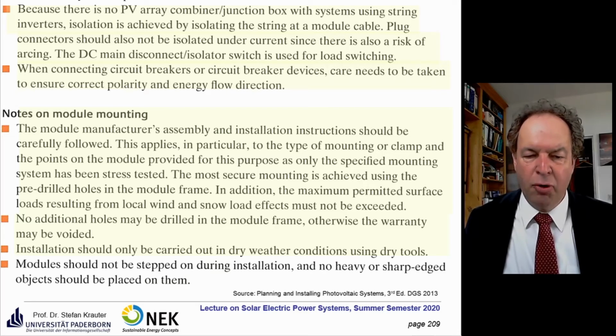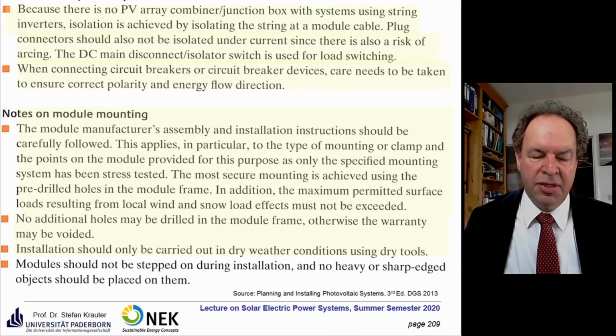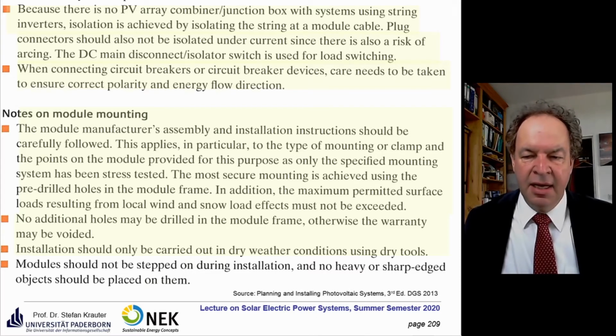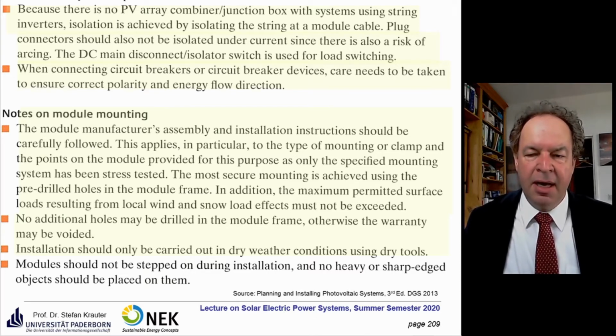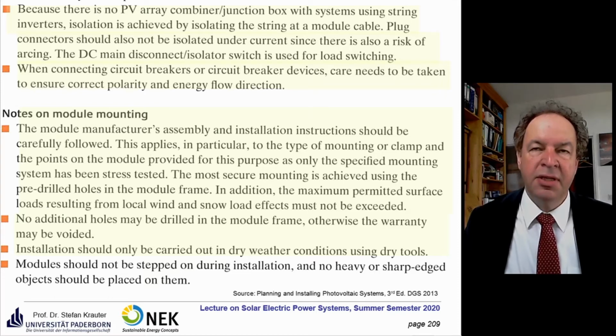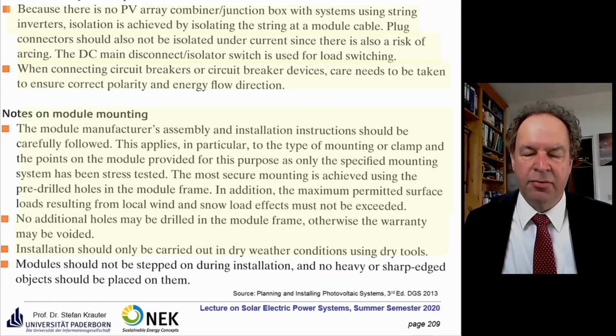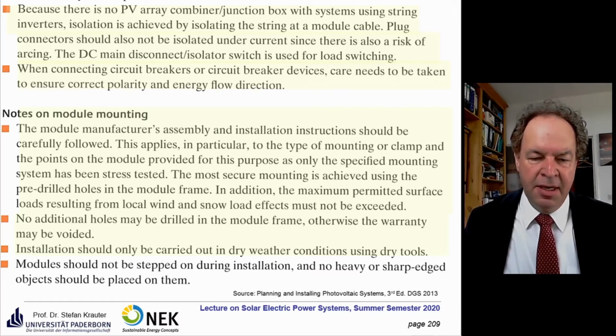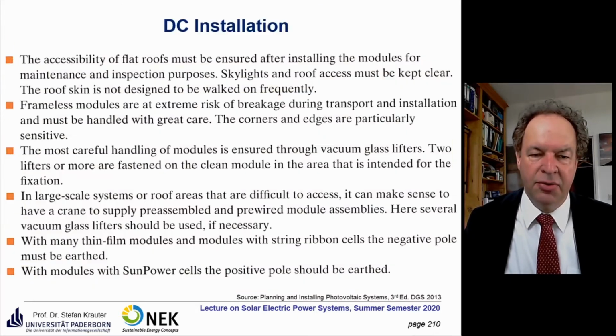This is more true than it was some years ago, because the cell thickness has become less, and so the risk of micro cracking of a cell is much higher than it was some decades ago. Sure, it's quite obvious you should not put heavy or sharp-edged objects close to them.